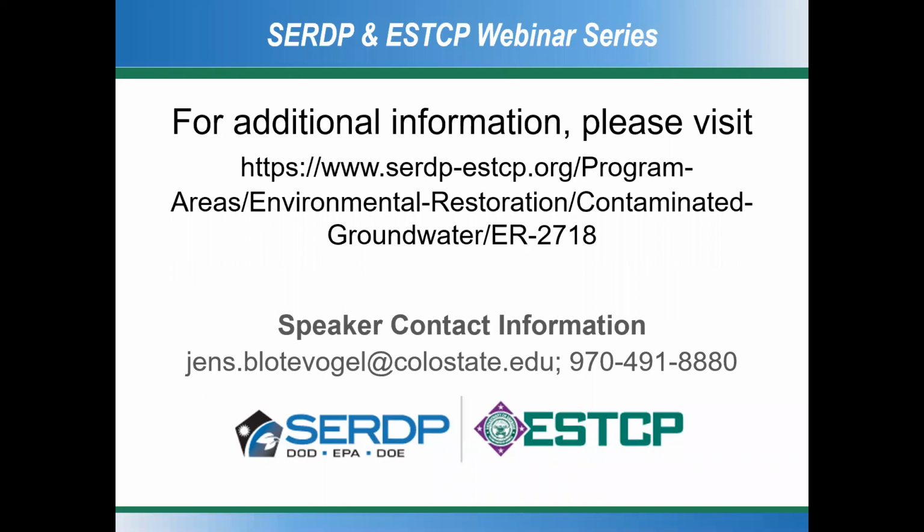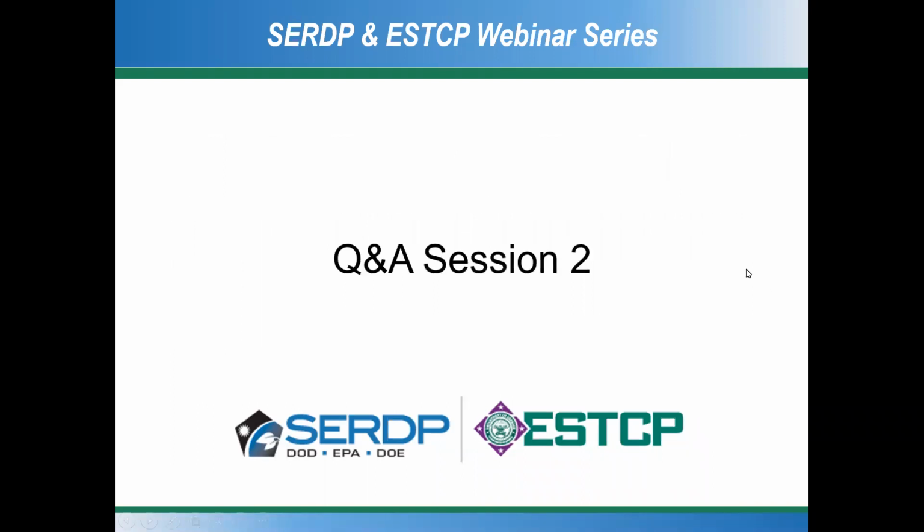Iron can always be a problem if present at high concentration because you may form sludge in reactors, and then you would need some means of sludge removal. The iron can also precipitate on the cathode, and so can carbonate scale. So the anode is of concern when it comes to iron oxidation. The cathode is of concern when it comes to carbonate precipitation because you have high pH values.